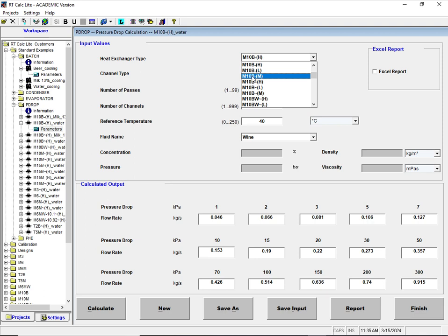But in reality, if you go to the actual people in the aftermarket who make most of the plates today, they find slightly different values to these values here. And funnily enough, some of these values are also idealized values by the OEM manufacturers. But in reality, over the years, the sizes are a little bit different. Some of the manufacturers might have different pressing depths, for instance, or slight changes in chevron angle. Chevron pitch also changes slightly. So in reality, these give slightly different responses. And you can play with that and see what the responses look like by adjusting.